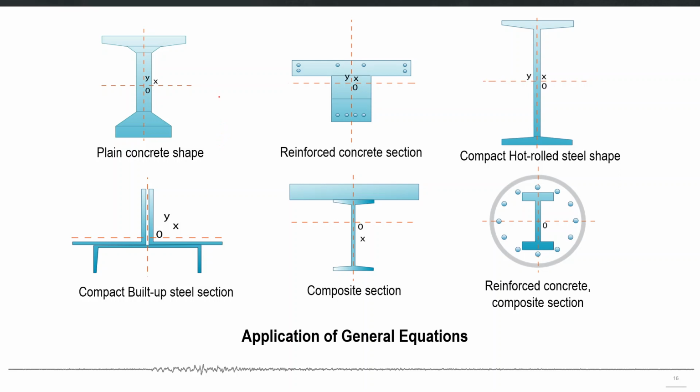One very common example of the Section Designer is when you retrofit a cross section, for example you apply column jacketing or increase the cross-sectional reinforcement or the cross-sectional size. You can always analyze that new cross-section in the Section Designer and compare its result with the previous cross-section.